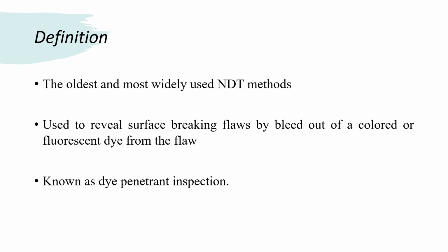In order to locate the area, the excess fluid is removed and the background must have sufficient contrast, thus leading to distinct detection of the defect on the surface. So this is basically used to reveal surface breaking flaws by bleed out of a colored or fluorescent dye from the flaw. This is known as dye penetrant inspection.